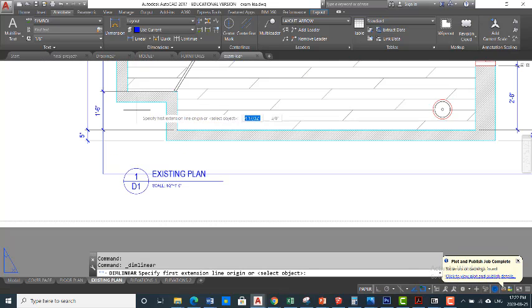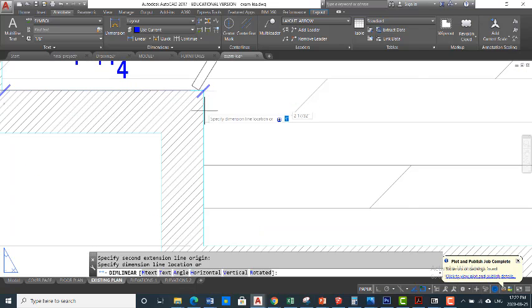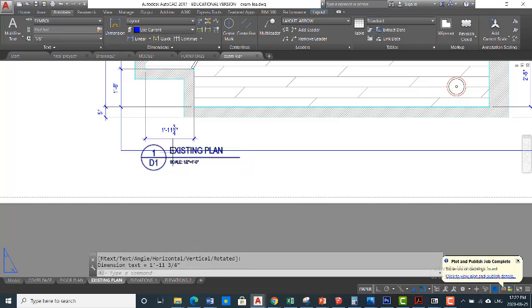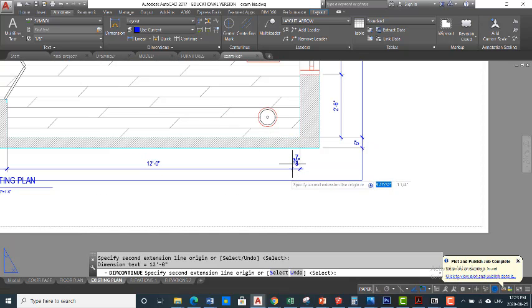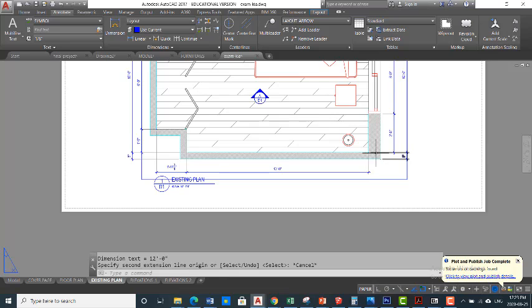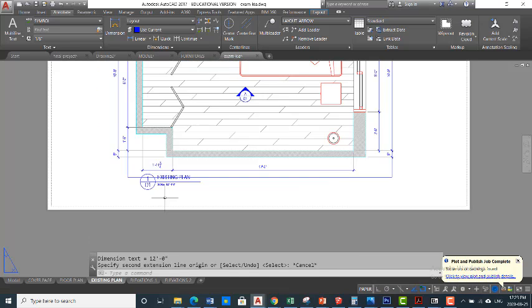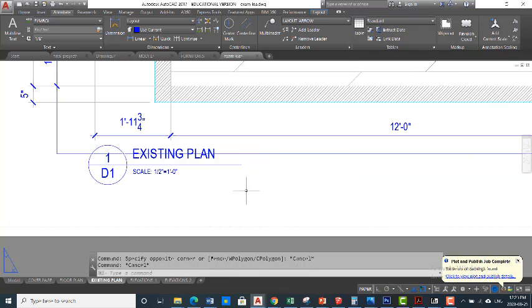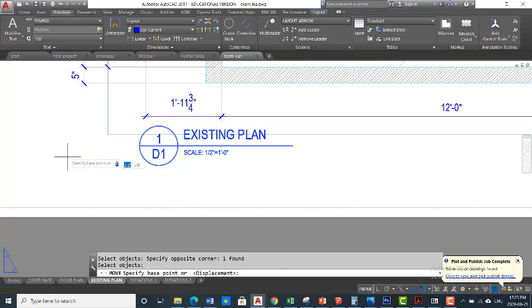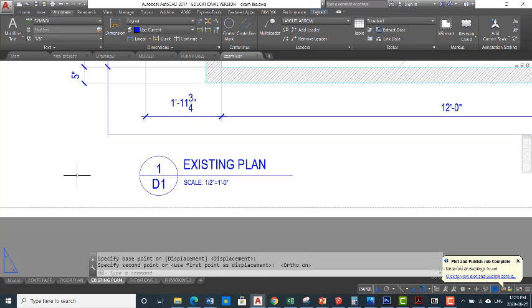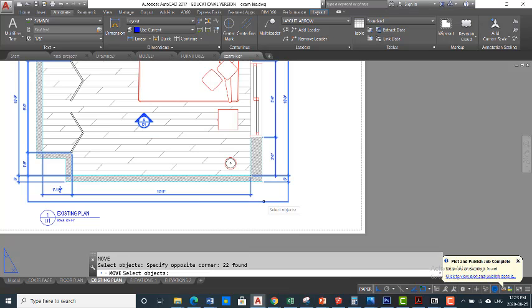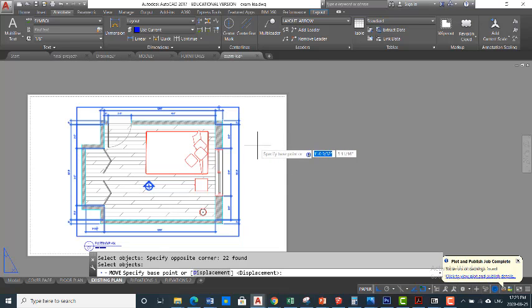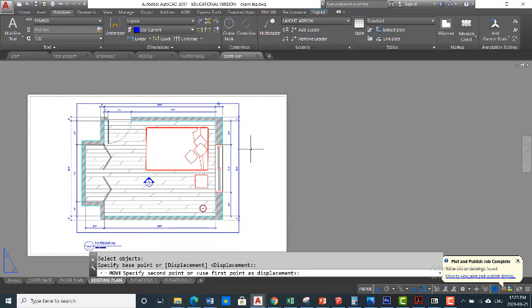Then I come down and add the dimension here. Okay, put it here. Maybe I move this later a little bit lower. Continue to here. Or you know what? I don't need it. I have the thickness of the wall. If I really want to do it, I move this one a little bit lower. And even if I want, I can move the plan. Say open a window like that, so that my window has my viewport and all the dimensions. Accept it.